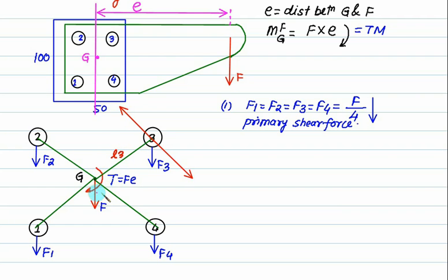This one is a clockwise moment, so I will retain this one, equal to F3 prime, and this I will cancel out, because if I use this one the moment will be anti-clockwise, but if I use this one my moment is clockwise. So cancel this. About this point, we want the moment at this point, this one equals what? L4.